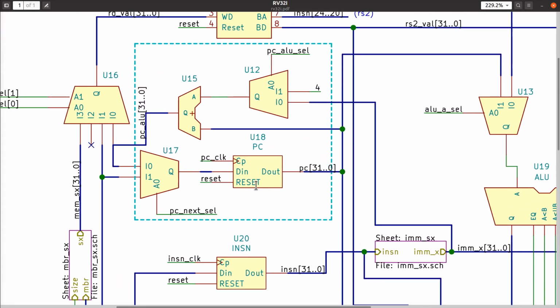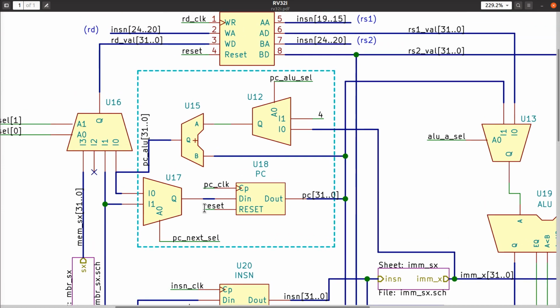It means that the program counter, whenever we want, can either be loaded with a value from the ALU that might be calculating some mathematical operation on some registers or something, like in the target of a branch instruction, or it can come from this adder over here. And we mentioned this before. You can put a separate little adder, a mini ALU that only knows how to add, for example, and it can know how to add something from this multiplexer to the program counter value itself down here.